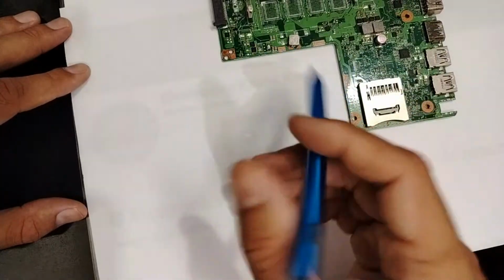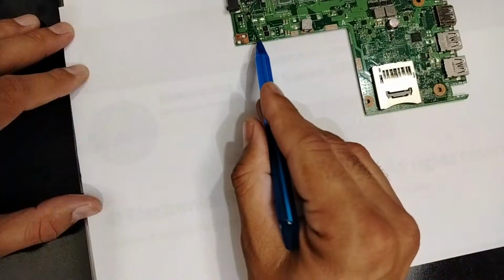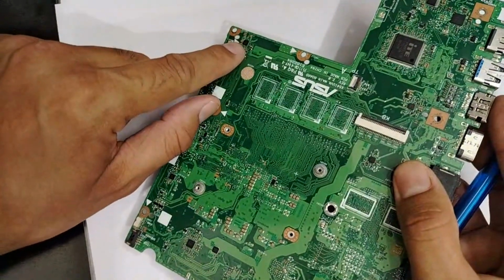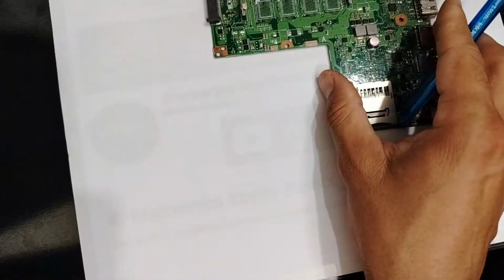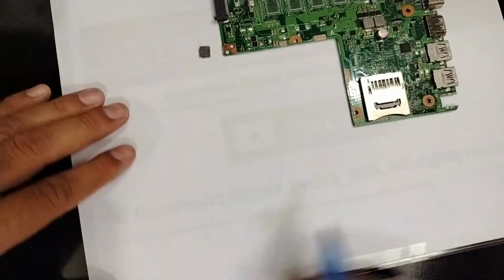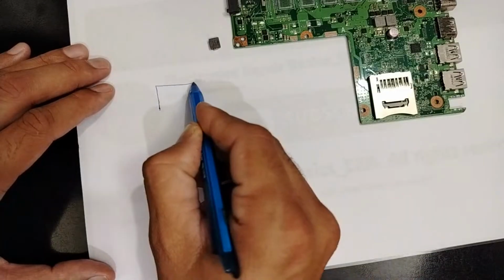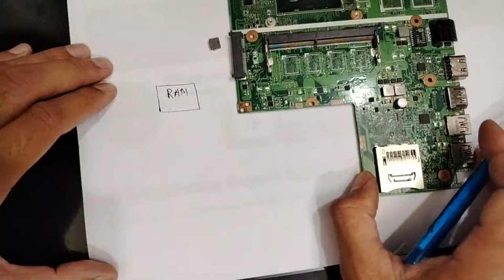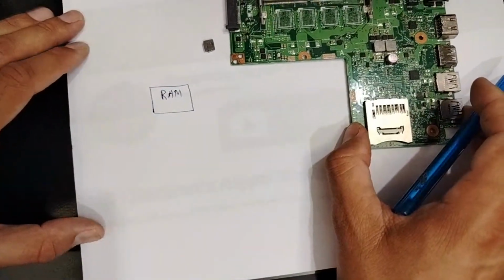Guys, the short circuit here, is this the same as this one? What do we have here? We have the IC in the back, surrounded by ceramic capacitors. Okay, let's draw the IC first. We have the IC like this. We call it the RAM IC because this circuit is for the RAM, but the same working principle applies to all circuits in the motherboard.